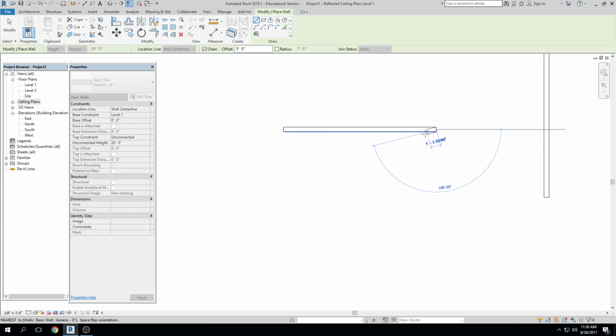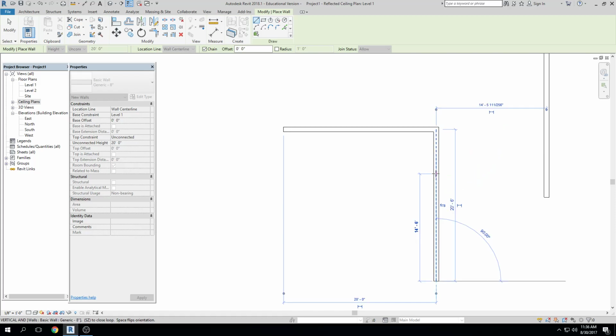So if I wanted to create something that is 20 feet 6 inches, I would type 20 space 6, right? Enter. Which is different from AutoCAD because it is forbidden to use the space bar, unless you want to hit enter. Yep. How do you keep the walls straight, like in a 90 degree? Like an ortho kind of thing.